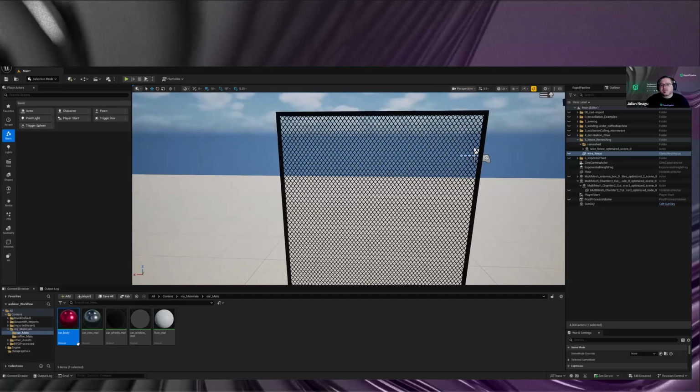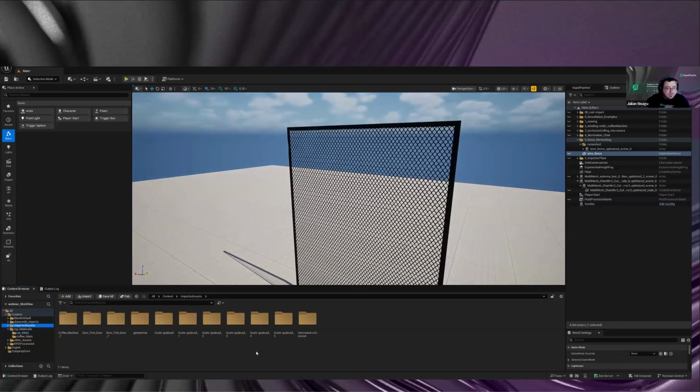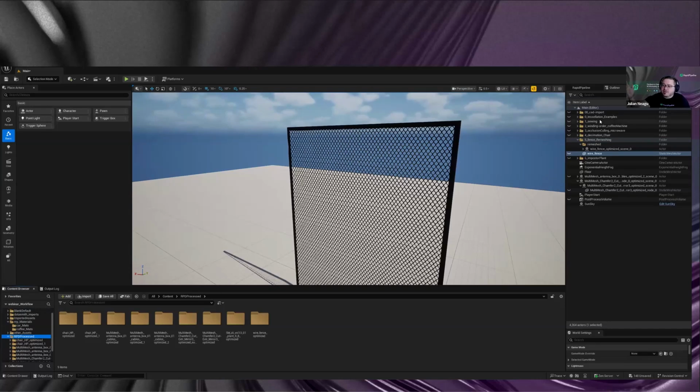And then, of course, as we have the objects in the outliner, you can always double check the actual file. Let me see where that is. I think it was stored under other assets and then under process. Yeah, there's one thing I didn't mention in the beginning. If you not only import something with an import action, but if you do a processing action, that stuff in the content browser is saved somewhere else. It's saved under RPD for RapidPipeline and then process. It's a different location where it saves that.